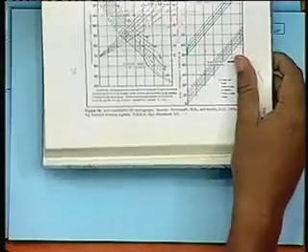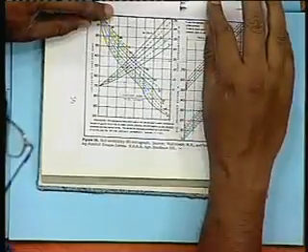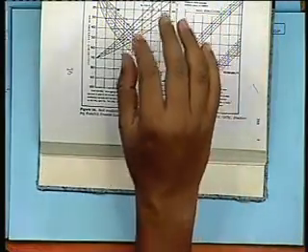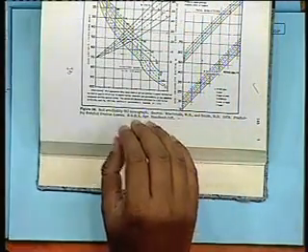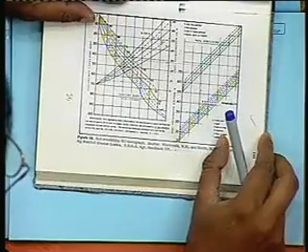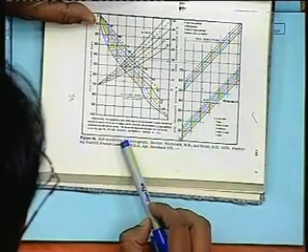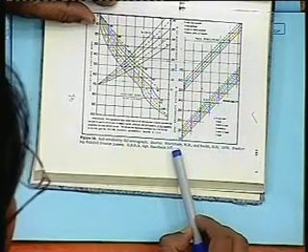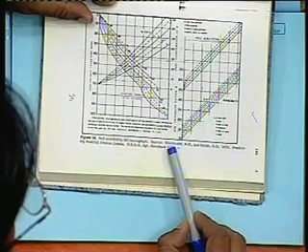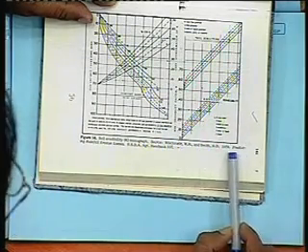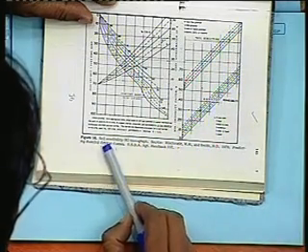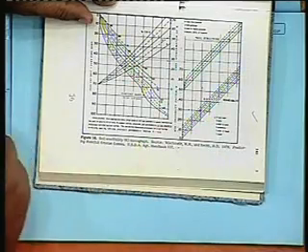Let me give you a brief example of how this soil erodibility factor can be found out. Just see this soil erodibility nomograph for K. It is from a very standard reference, Wischmeier and Smith, Predicting Rainfall Erosion Losses, USDA Agricultural Handbook.